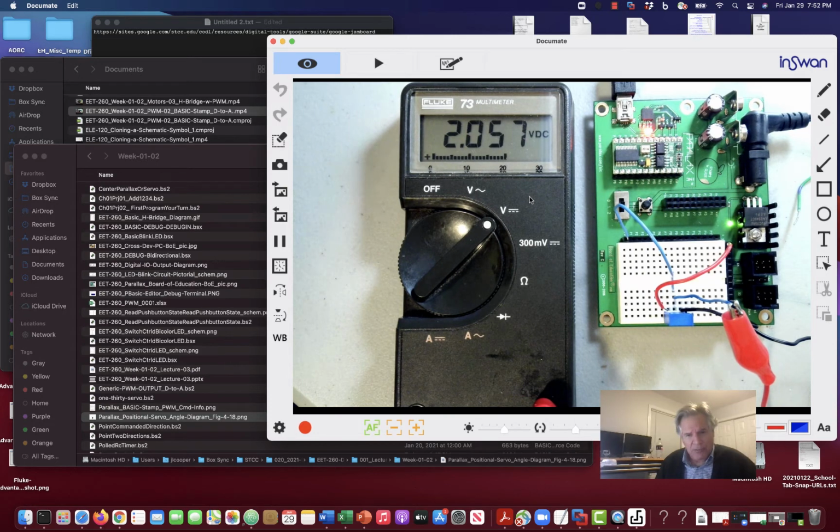and some high-end voltmeters that are multiple digits, like 6.5, 7, 8.5 digit voltmeters, use a technique called a dual slope integrating converter. And what you're doing when you pile that current into a capacitor, current is just electrons per second. It's charge per second, and capacitors are a bucket for charge. So if you can put the electrons in at a steady rate, then the voltage, which is proportional to the charge in the capacitor, will climb at a steady rate.